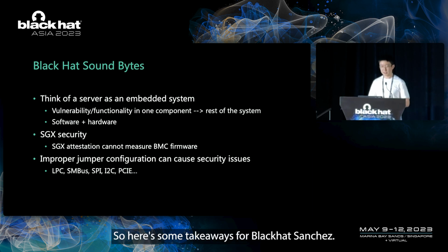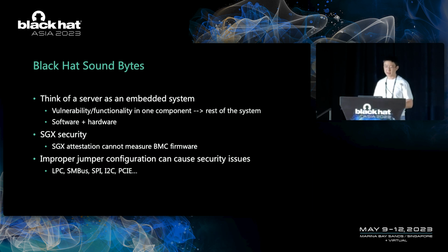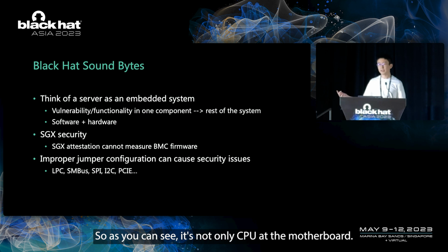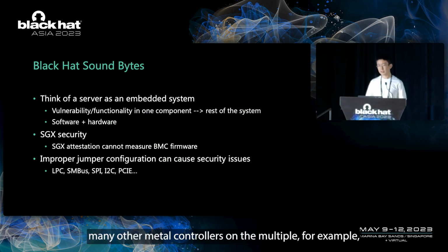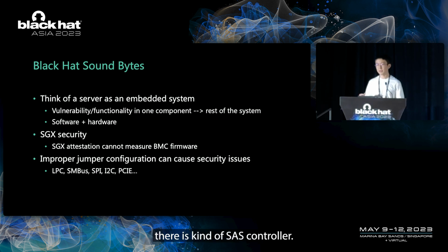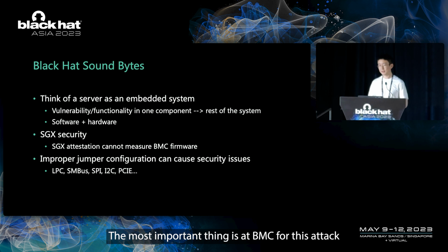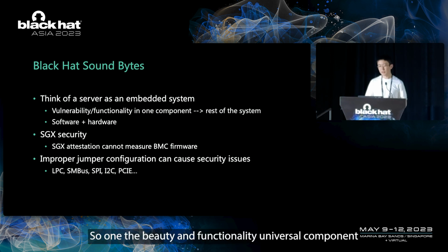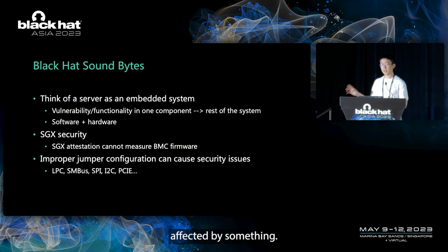So here are some takeaways for Black Hat soundbites. The first one is we need to think of a server as an embedded system. As you can see, there's not only the CPU on the motherboard, there are also many other microcontrollers, for example a SAS controller, and the most important one for this attack, the BMC. Sometimes there is also a CPLD on the motherboard. So vulnerability and functionality in one component can affect the rest of the system.